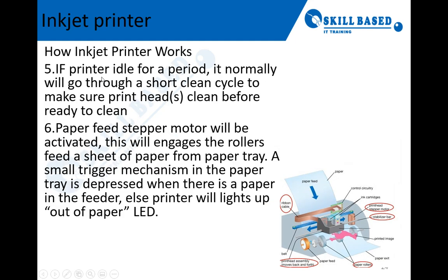If the printer has been sleeping or idle for some period, it will normally go through a short clean cycle. When you start, the printer will go left and right to clean the print head. After that the paper feed motors will be activated, and this will engage the rollers so they feed in the paper from the tray, and a small trigger mechanism detects whether the paper is in position or not.